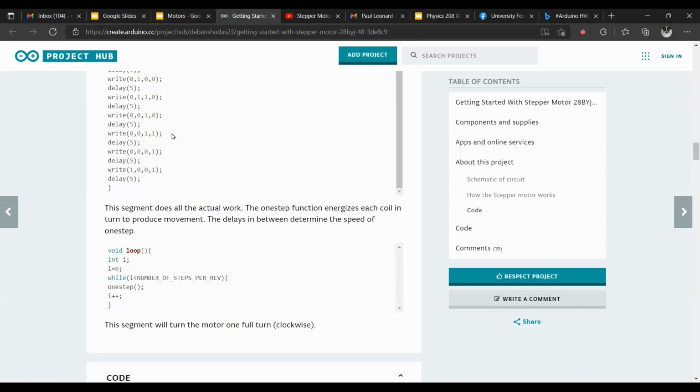So essentially, the gear that is in the stepper motor reduces the motion by 512. So, ibig sabihin, one full turn of this internal gear is just 1 over 512, okay? Or 360 divided by 512.